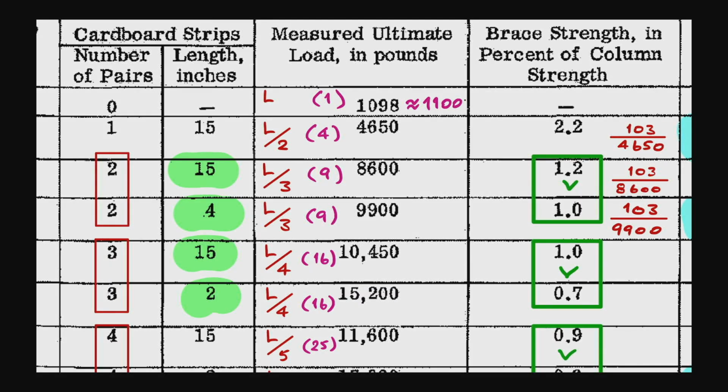So you see from 1100, if you multiply by 16, you'll get around 17,600. Approximately the numbers should be around here. But you find that it is just around 17,200. Okay, not too far from 17,600, but still this is less than that number quite significantly, and that is because the brace stiffness of 2 is not enough.